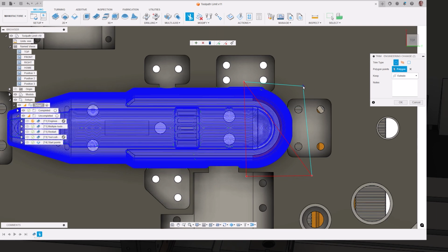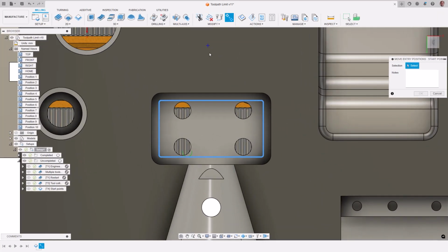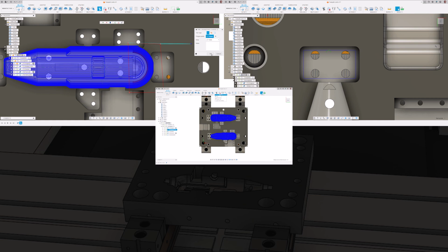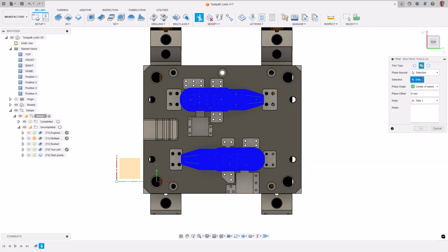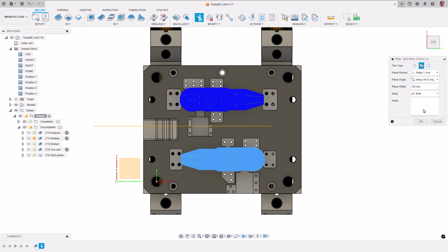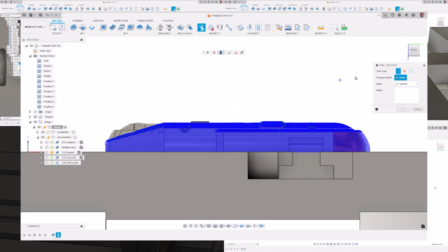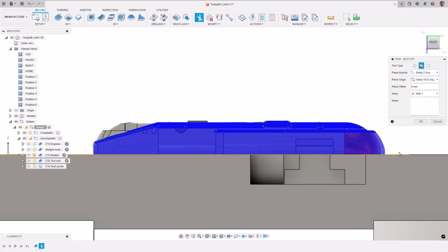The suite of modification tools allows you to quickly turn a good toolpath into an excellent one, without the need to recalculate the entire toolpath, thereby saving both time and effort. Trim or delete unneeded toolpath segments. Move start points to optimum locations, and quickly replace the assigned tool used by a toolpath so that it uses another tool with an alternative stickout or holder assembly.